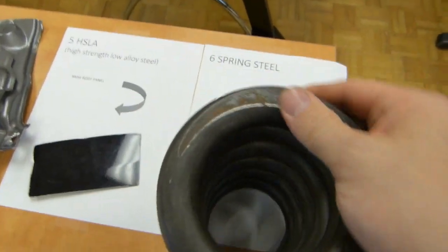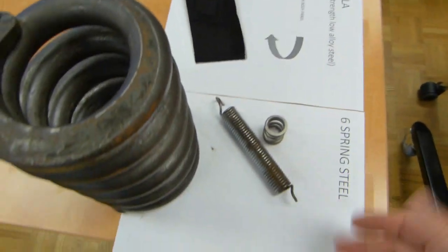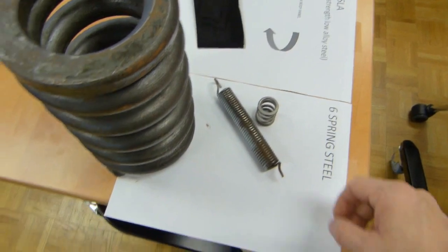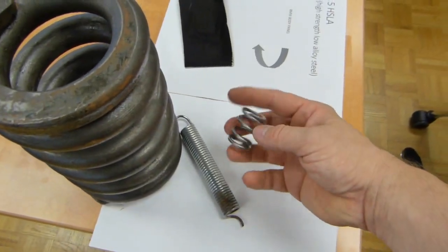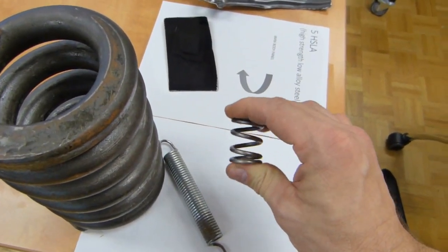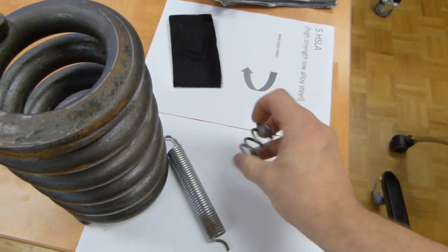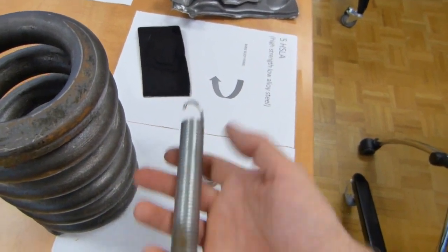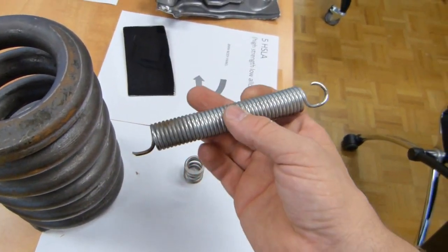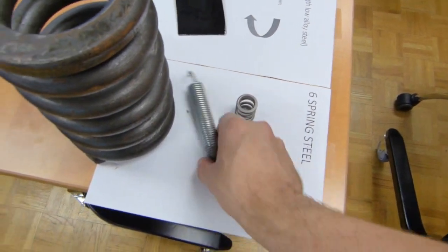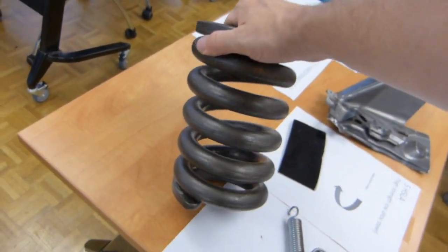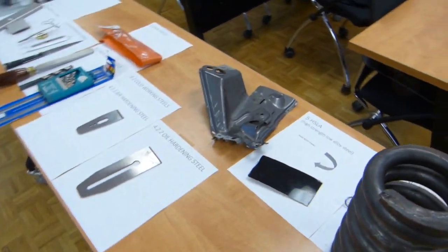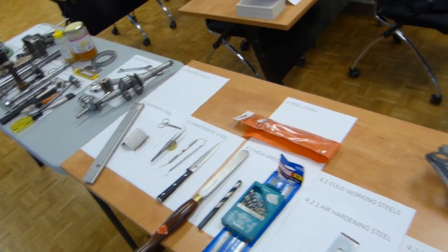Spring steels, yeah, don't mess with them. They have too much carbon. If they break, tragic, get a new one. So they're not weldable. Yeah, end of story about springs. This one is a compression spring. You can see the coils will get closer. This one is a coil that's for extending. It's an extension spring from a sofa or something, had a hook failure on it. And this one's from an elevator shaft. It's from an elevator. Alright, so that's basically what I wanted to share about the weldability of these things.